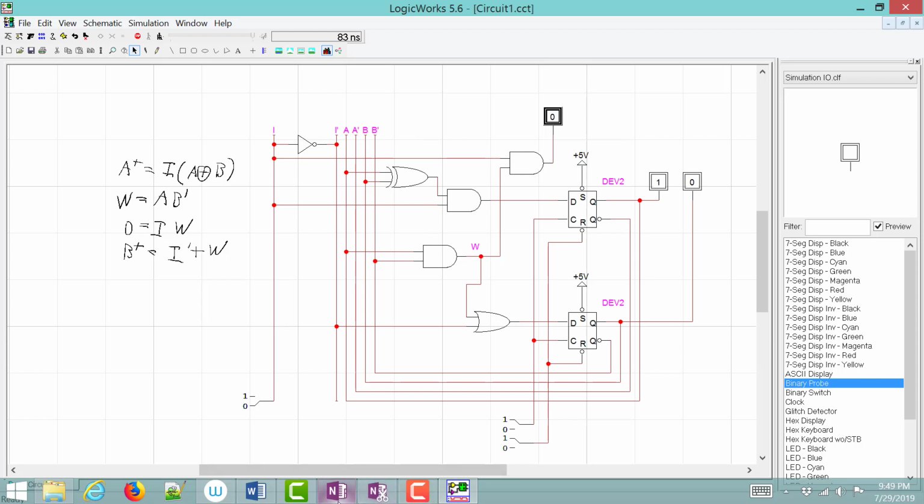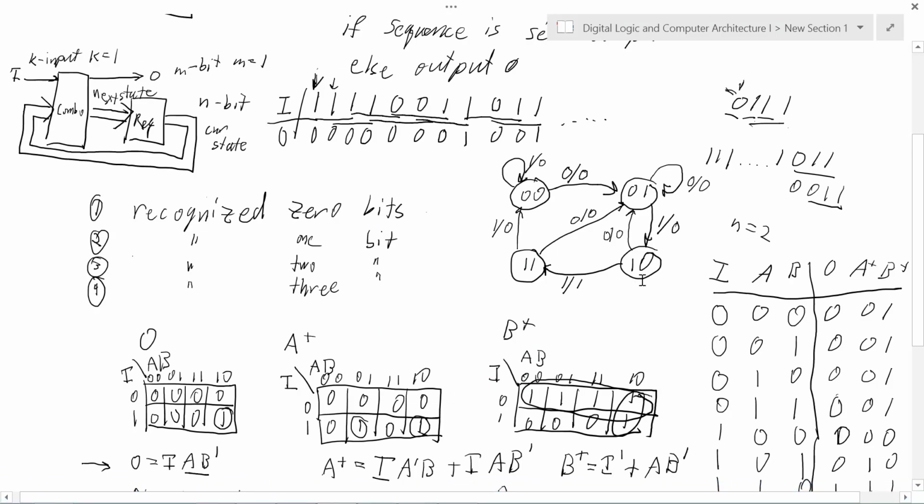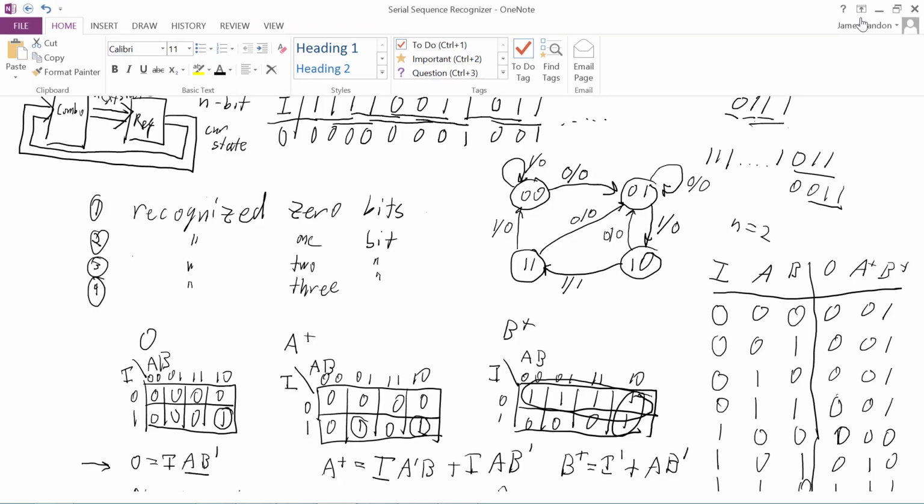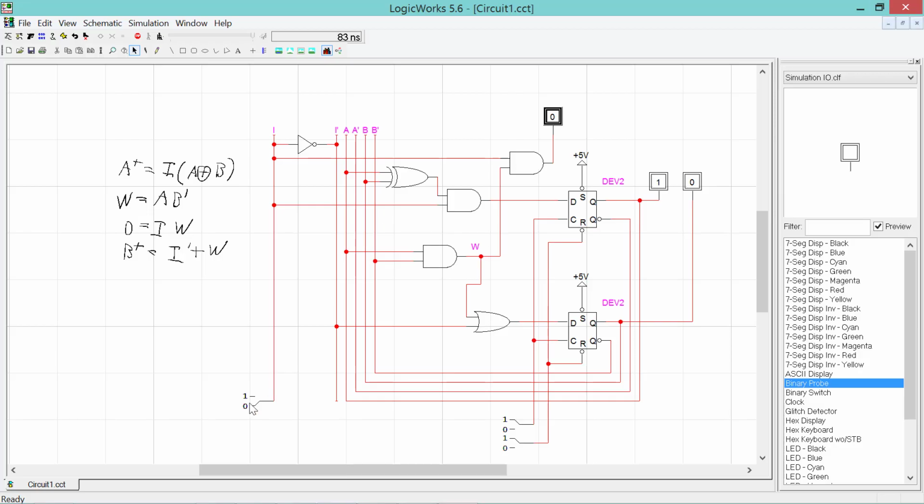So coming back, we are in state 1, 0. If we input a 0, we output a 0 and go to state 0, 1. So when clocking, we are looking at an output of 0. 1, 0, we should clock back and it should go to state 0, 1. We are in 0, 1 now. Changing the input pin doesn't have an effect because the output value is always the same for state 0, 1.